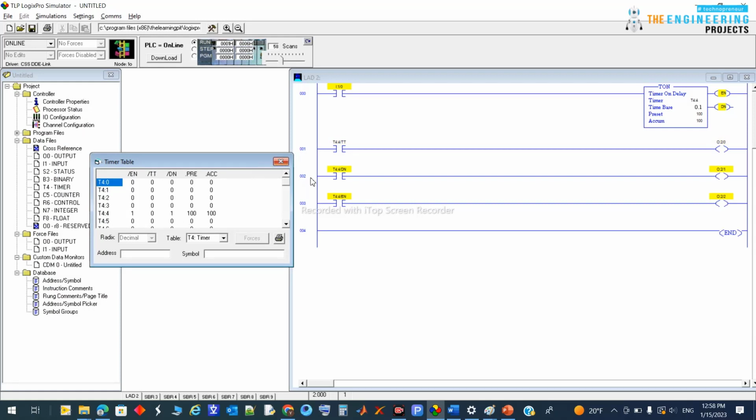So that's for showing everything in the data file of RSLogix, and also how to use the different timer bits to enable activating outputs, which are the most important bits: the timing bit, the timer done bit, and the enable bit.